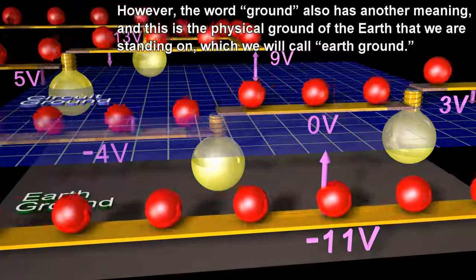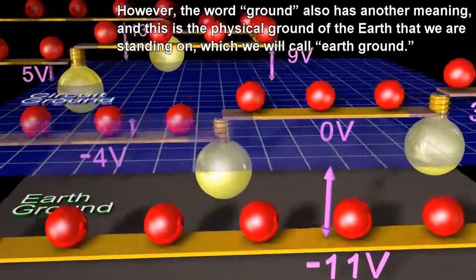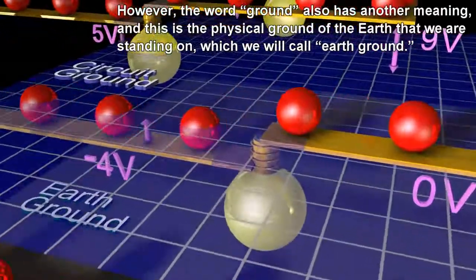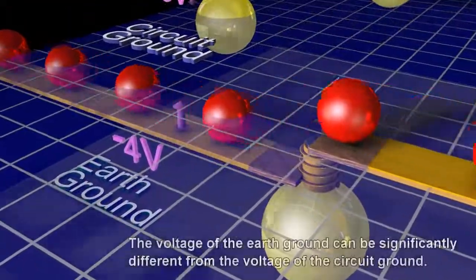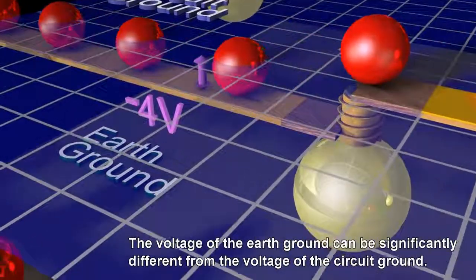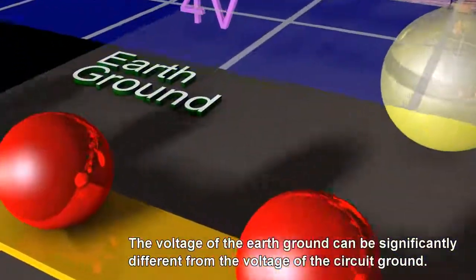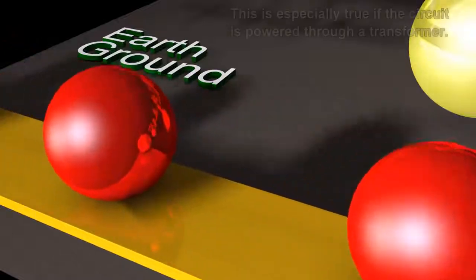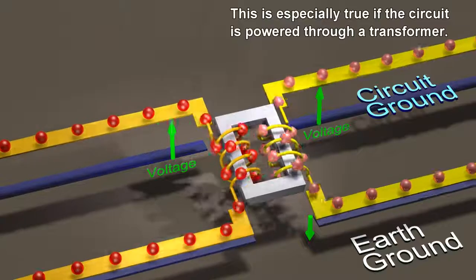However, the word ground also has another meaning, and this is the physical ground of the earth that we are standing on, which we will call earth ground. The voltage of the earth ground can be significantly different from the voltage of the circuit ground. This is especially true if the circuit is powered through a transformer.